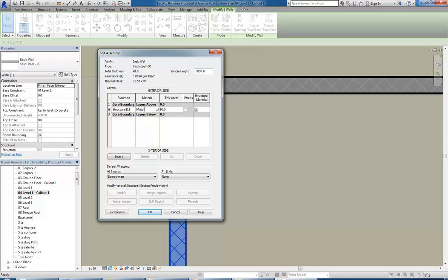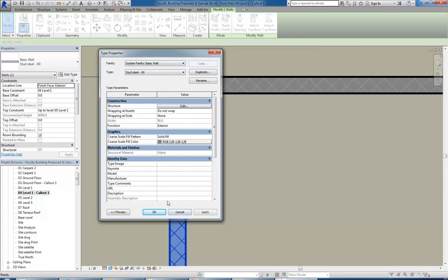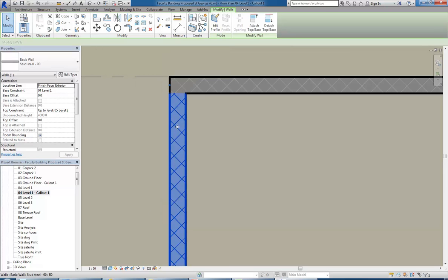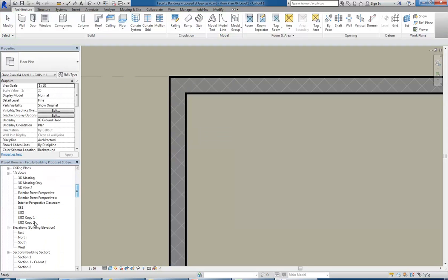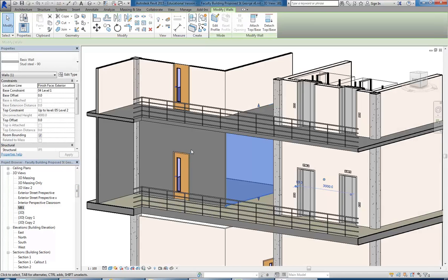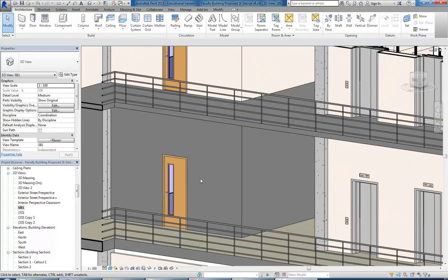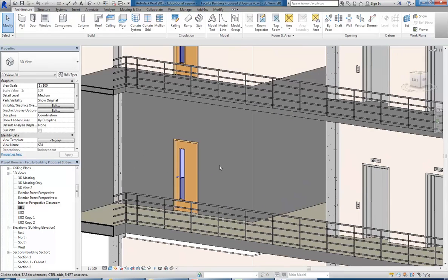that you have sometimes just one layer for a wall, even though you know there are many components in the wall, because you have all those options in Revit for setting one material for the cut pattern to one thing, and then the surface pattern, and also the shading colour to something else. And so that way you can get a plain surface on the outside while it's still showing the cut pattern.